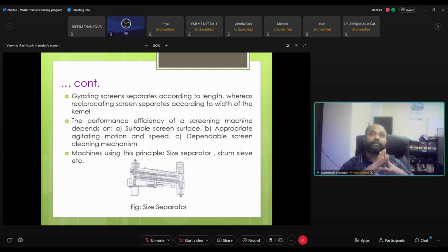Basically, in the ship unloading systems, wherein the material comes in ships, it needs to be cleaned at the port itself, right? Because the time of ship unloading will be restricted to one day or so, and the ships come in capacities of maybe 500 tons, maybe even 50,000 tons or 60,000 tons, right? So in those kinds of situations, drums are used. Of course, in higher grain processing capacities like wheat milling, drums are also used as pre-cleaning equipment. So this is mostly about the cleaning principle.